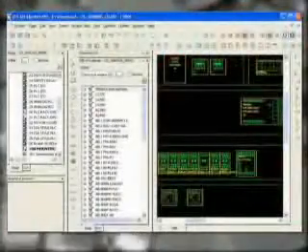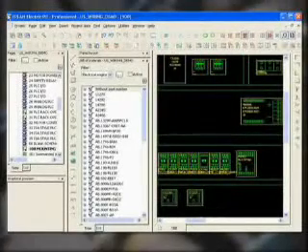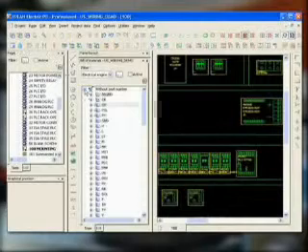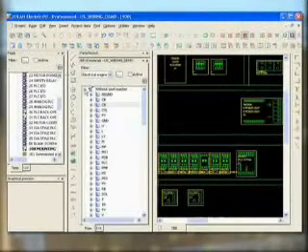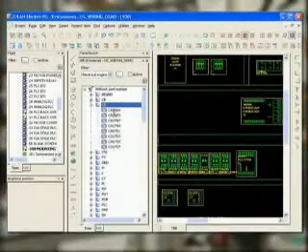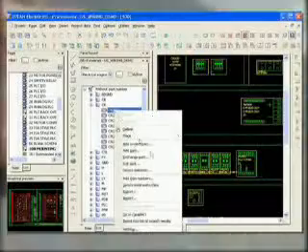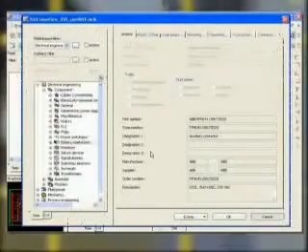Using Eplan Electric P8 with the bill of materials and panel layout navigators, you can design your panel and be sure that you'll never miss a part. The bill of materials navigator shows you all of the parts that are used in your project. It also has a list that shows all of your components that need a part number. You can even add this part number directly from the navigator.